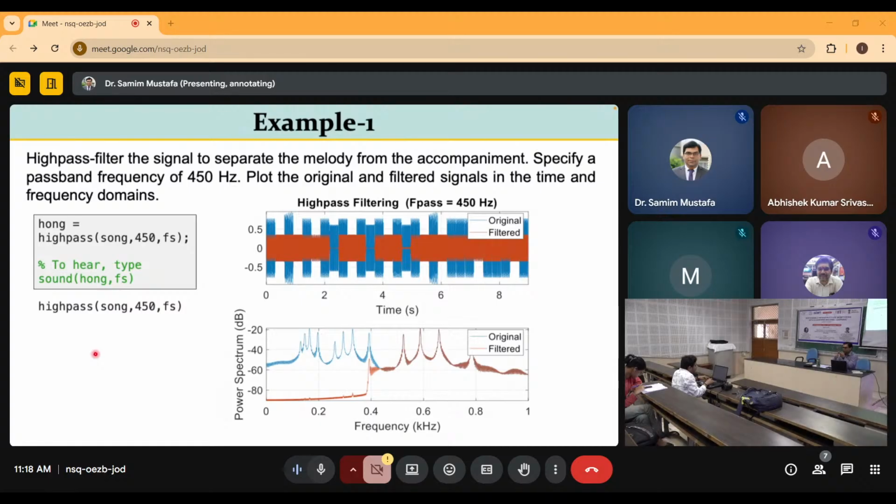Because first frequency is the lowest, then second will be slightly higher, and so on. So bridge has a lot of frequencies, as you know. We can only measure some of them because we can excite the entire bridge only to a certain extent. So probably few modes, 5 or 6 modes, initially we can measure from the experiment.